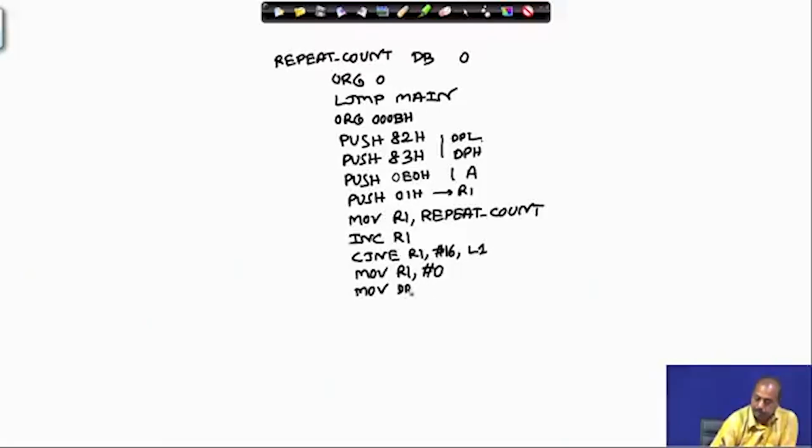So, move DPTR comma #8002 hex. Then movx A comma @DPTR.